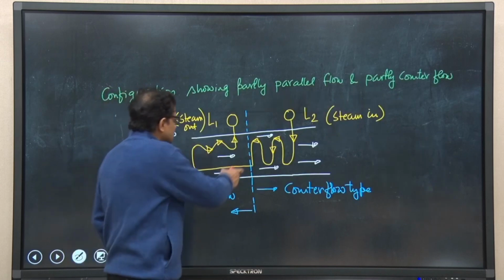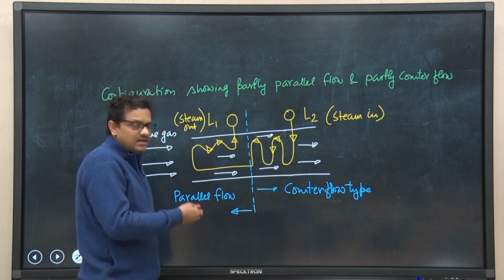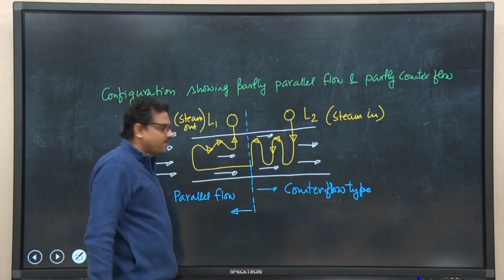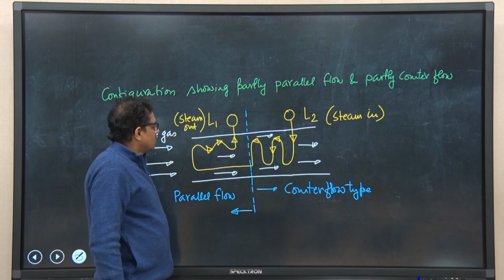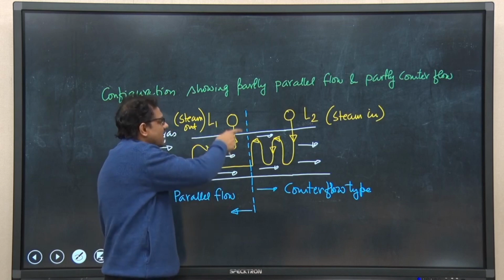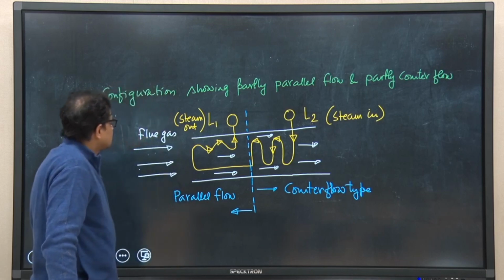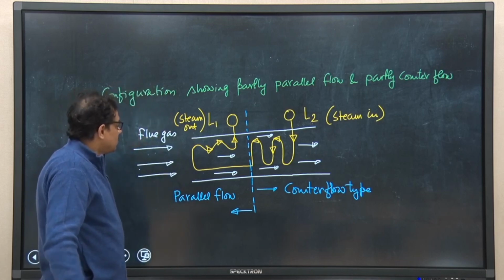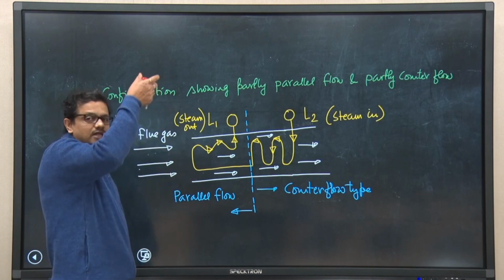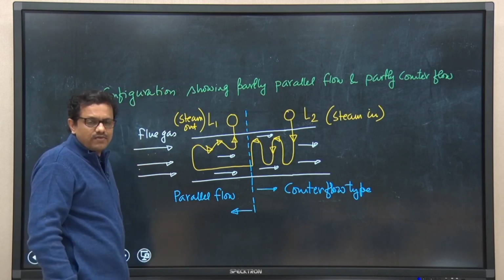This one is also the same, but a little different, as we have discussed that it is having both counter flow and parallel flow type arrangements. So, even in this case the entire coil is placed inside the confined chamber and the coil is suspended from the roof of the boiler. But in all these 3 cases, you know that the coil is vertical type, as if the coil is suspended from the roof and placed in the confined space wherein the flue gas will be flowing.